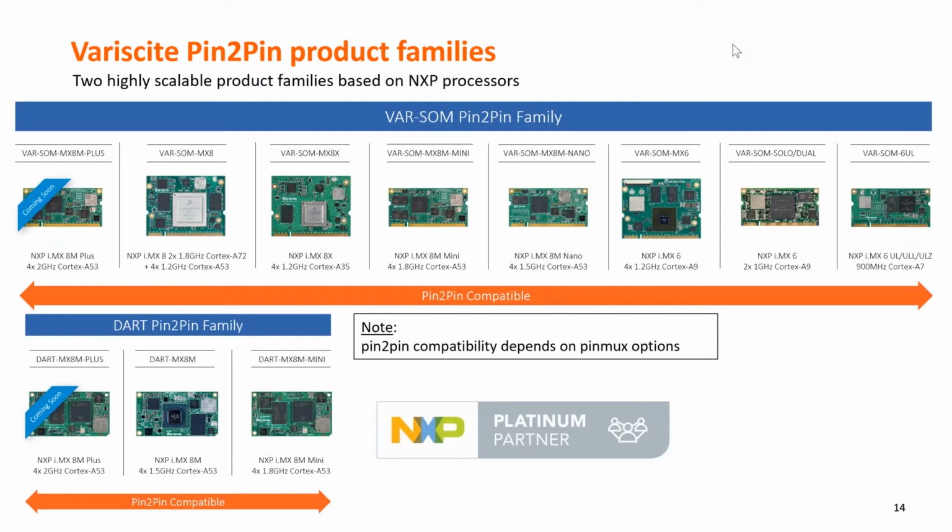Same goes for the Dart pin-to-pin that you have here below, which practically gives the customers the ability to design a carrier board that can be scaled up from the different processors that you have today, but you can also count on the fact that if there will be an i.MX 9 or when there will be an i.MX 9, 10, we will keep the pin-to-pin scalability that you're practically using today to be used and scale up to the future processors coming from NXP. And this is the concept of the pin-to-pin compatibility.